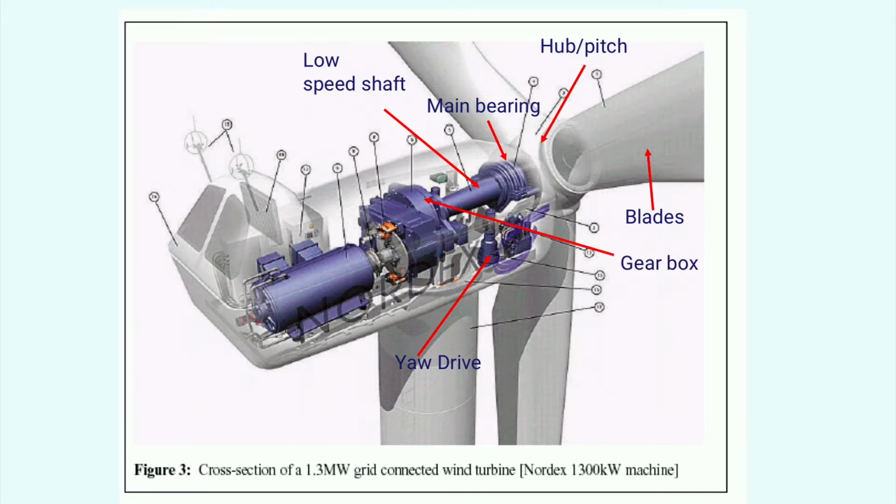The main shaft is often connected to a gearbox to step up the low-speed rotation to a high-speed rotation required by a traditional generator. Here you have a large mechanical component which is in service under variable loading conditions for most of its life. Compare that with the gearbox of a car which is idle in the garage for most of its life, and you begin to understand the conditions that a turbine must withstand over its 25-year lifespan.